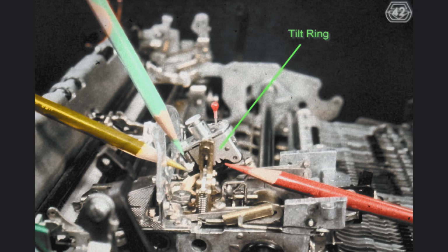The rotate detent will come up under the action of its own spring, indicated by the yellow pencil. This spring is called the rotate detent spring. The portion of the rotate detent indicated by the green pencil engages with the teeth of the type element, or the skirt of the type element. The purpose is to lock the element in any one of the tilt planes during printing. The red pencil indicates the portion of the rotate detent which is acted upon by the tilt detent, whenever the tilt detent disengages the rotate detent after printing has been carried out.